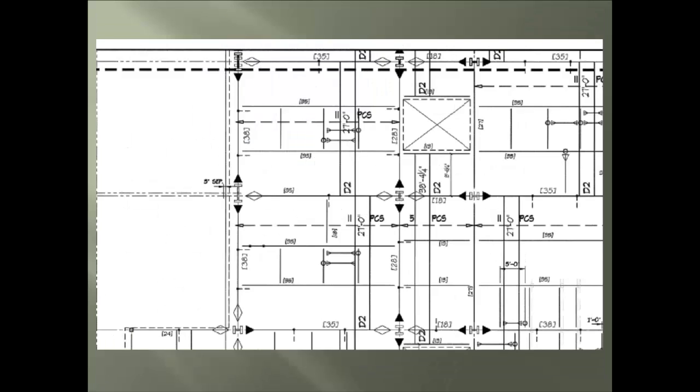There must always be some type of support under the metal decking, so we have 4 columns that will connect with 4 beams. Here we see the symbol call out for the D2 type decking required in this section. And here's the bundle outline that is supported by the beams at each end.